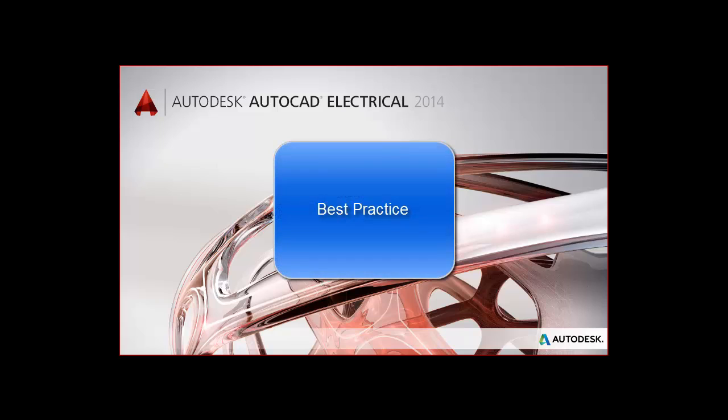It is a best practice to save your plot list as a DSD file in the project directory where the drawings reside so that the list and configuration can be used again in the future or by others. Page setups are crucial to this process and must be created before attempting to do a batch plot or publish. How to create page setups is covered in a different tutorial.